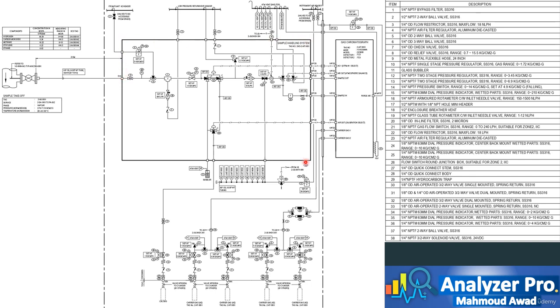First we have an isolation valve, then the pressure gauge, then a 3-way ball valve that switches between the sample gas or nitrogen used for purging or cleaning during maintenance periods. Then the sample reaches the bypass filter, divided into 2 directions: the direction of the analyzer and the direction of the return point, through a bypass flow meter with a needle valve to control the bypass flow as per the lag time calculation requirements, and a check valve to a low pressure return header.